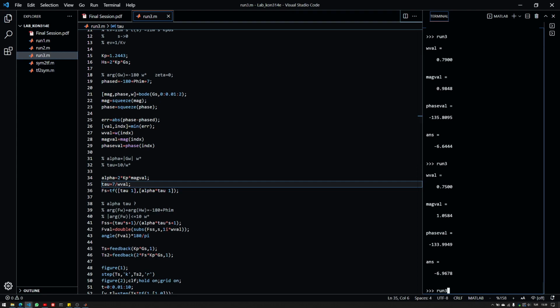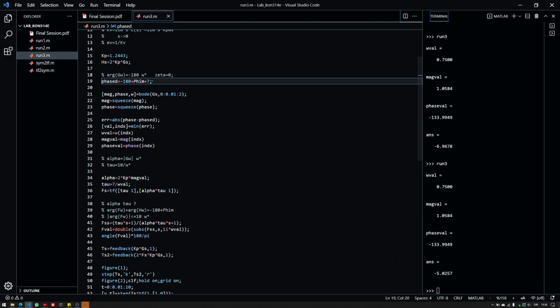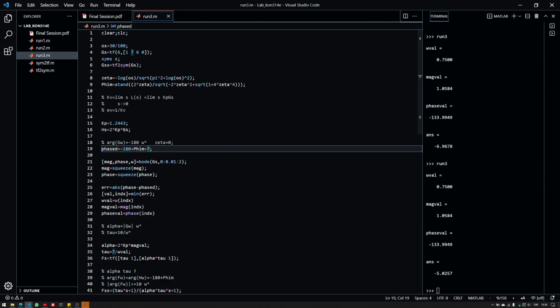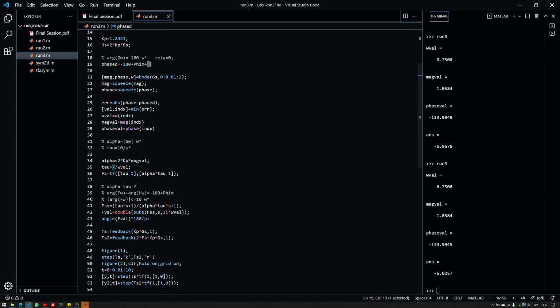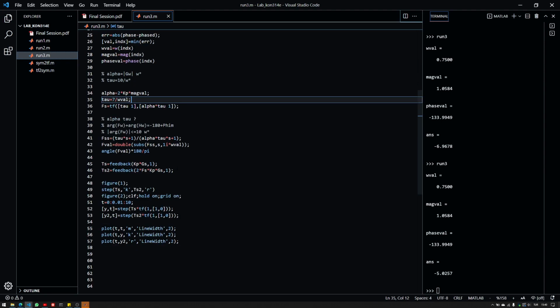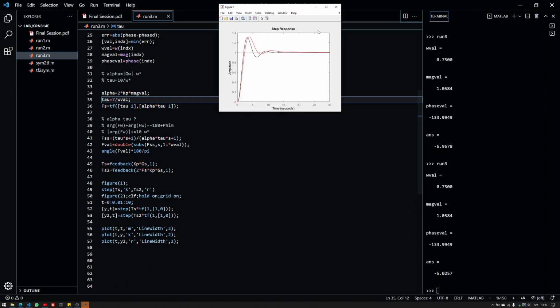Maybe there's still some stuff to do here. Yeah, you can see that you will eventually end up in a point where you have exactly the value that you used here. So 7 is a bit too much. Use 6 and iterate through it. But if you're on an exam, I would recommend you to use 10. Then check if your controller holds the assumption, and you can leave it there, because we have MATLAB and we can do it over and over again, but in the exam you would basically not do it. So, and we didn't touch too much the overshoot value. It is even closer now.